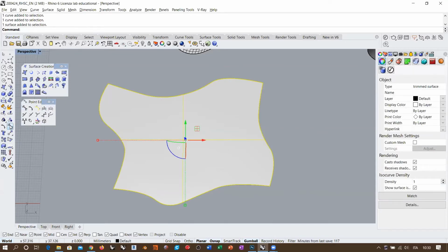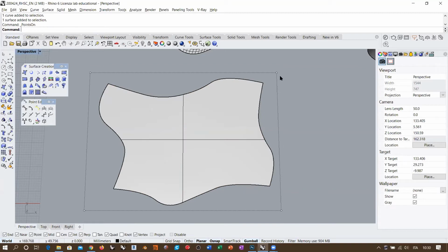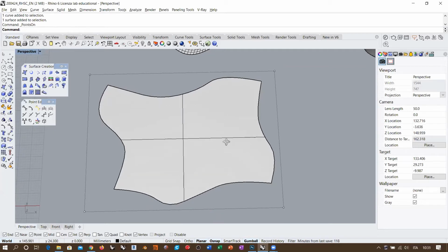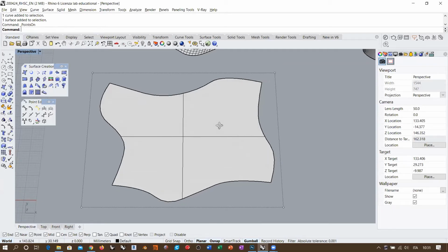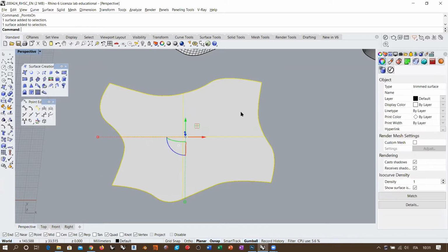So if I activate the control points, I see that the actual surface reaches this outline here, which is the rectangle. And then this rectangular surface is being trimmed with this silhouette here. Now, this being a rectangular, trimmed surface, it means that its topology does not correspond exactly to the boundary of the surface that I see. Trimmed surfaces are, let's say, a visual operation where you see the final result, but the topology stays untouched, right? So this being a rectangular surface, it has no deformation possibility on the inside, because there are no internal control points.